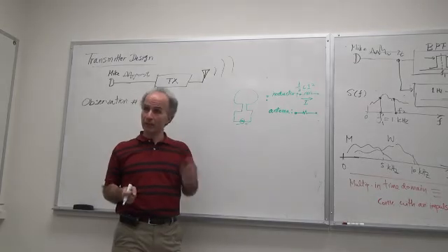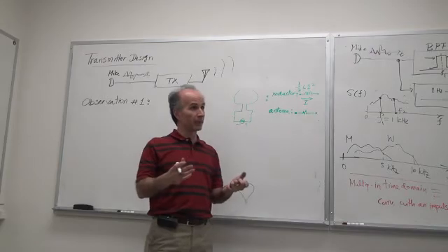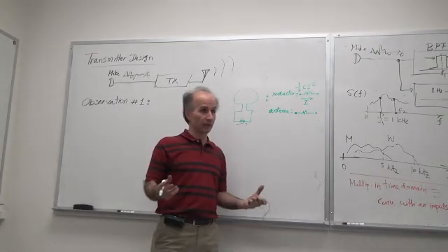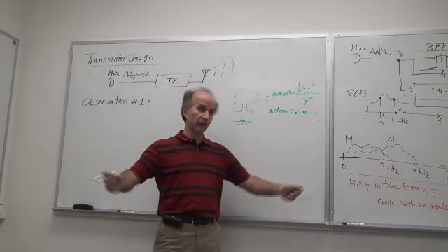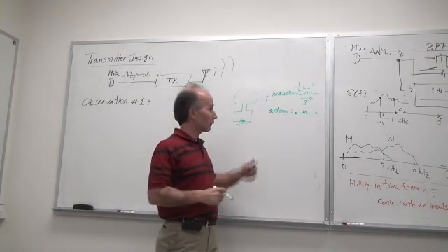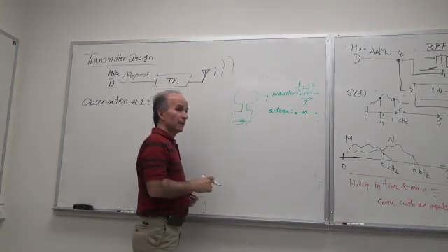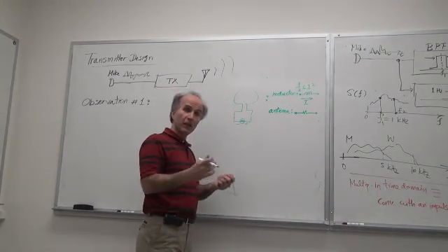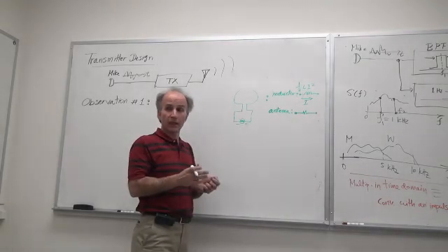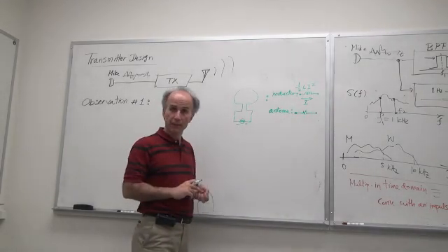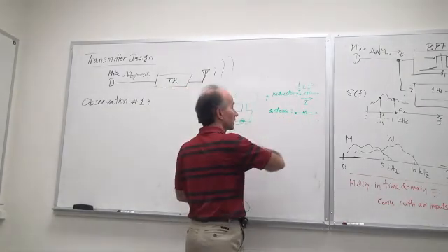If you really had a physical resistor, and you applied a voltage to it, what would happen? The resistor would heat up. The heat comes out in the form of infrared. Infrared is an electromagnetic signal, except that it has a very long wavelength, right? Well, not as long as our 1 gigahertz waveforms. Now, if you give a 1 gigahertz waveform to this antenna, and it dissipates it, it radiates it, it still radiates in an electromagnetic form, except that it's not infrared, it's some lower frequency, 1 gigahertz or something, right? So an antenna, a good antenna is a resistor.